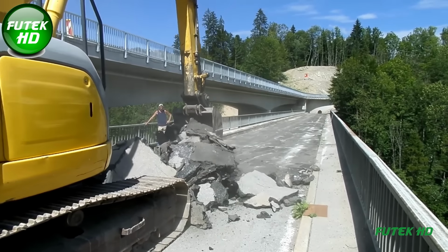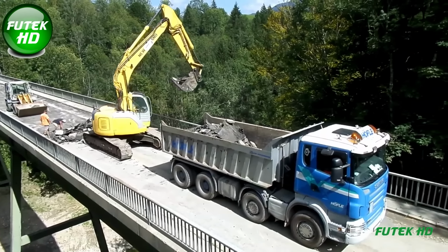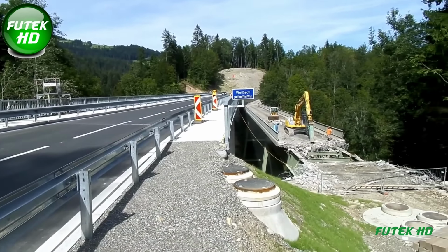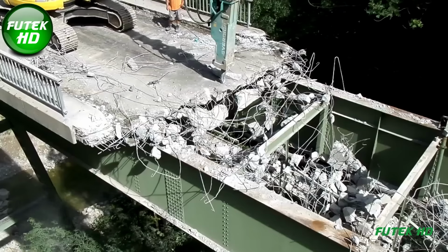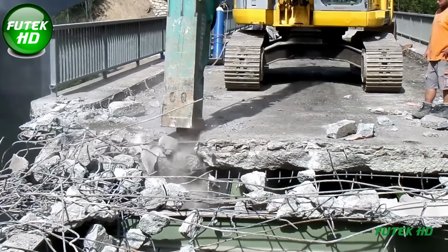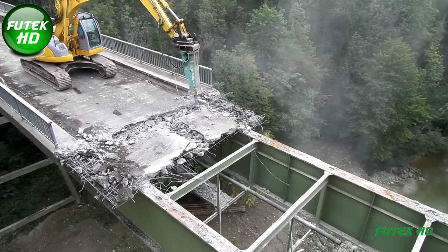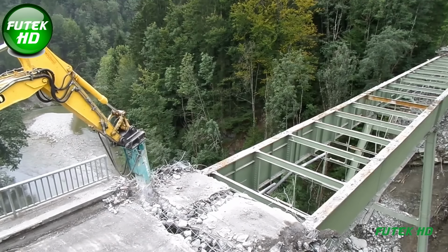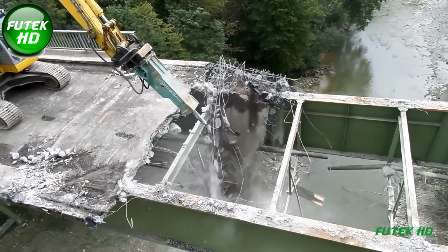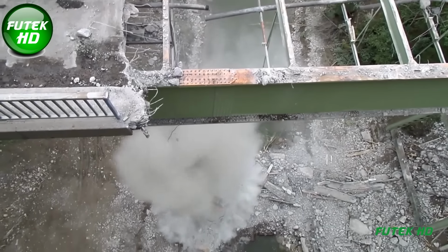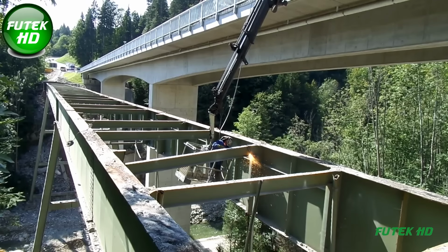Demolition of the old bridge and renaturation, October 2015. In late August 2015, the final phase of the project began with the demolition of the old Brunsttobelbridge. This task required careful planning to avoid compromising the stability of the steel structures. The initial demolition focused on removing the asphalt and concrete slabs, followed by separating and lifting out the cross-girder assemblies and main girders. Pendulum supports were secured with steel cables and subsequently dismantled and removed.